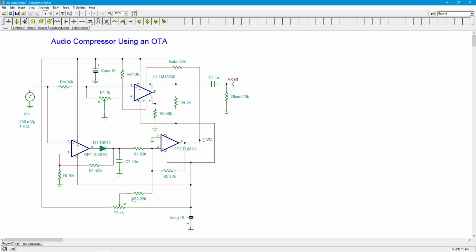Now, if you don't have this at all, like if you just got rid of R2 and P2, the minimal value out of here, let's call it the 0 signal level, would be halfway for VC. VC can essentially vary between the power supply rails. Not quite, but pretty close. So you'd only be using half the range.